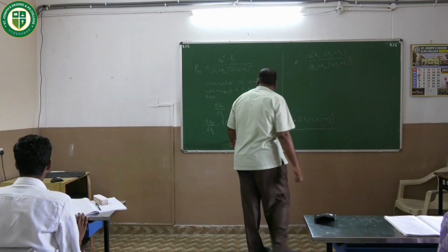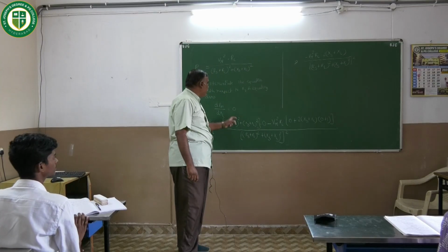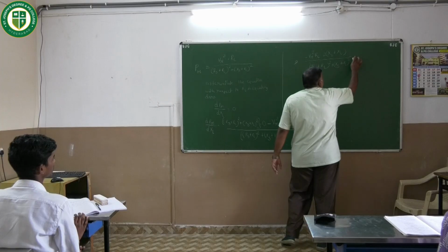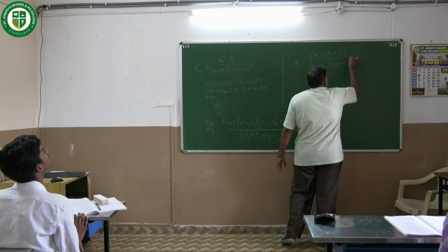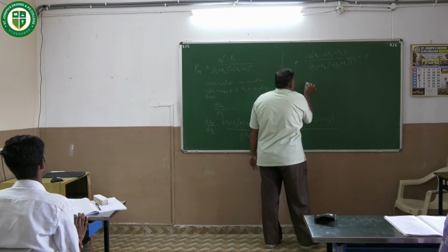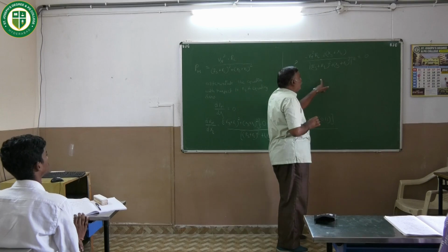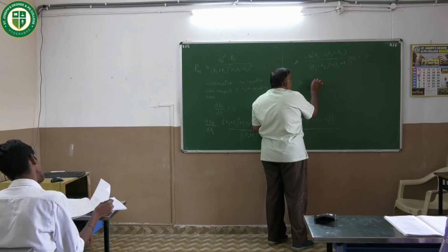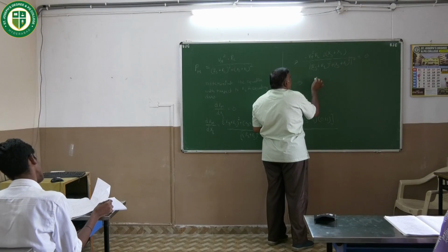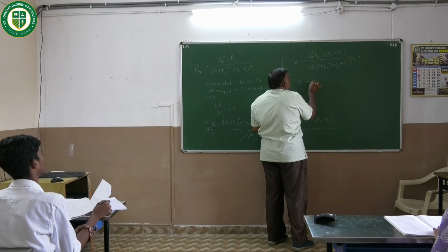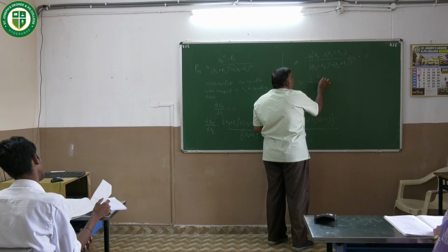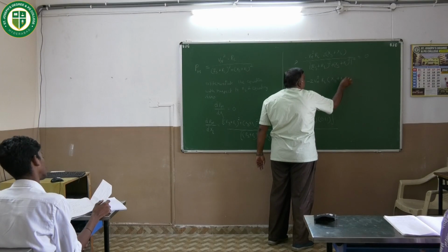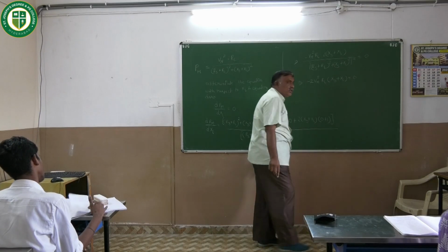Now once the differentiation is completed, I need to equate it to 0. So here, if I take the cross multiplication, it is minus 2 Vm square into RL into (XS plus XL) is equal to 0.